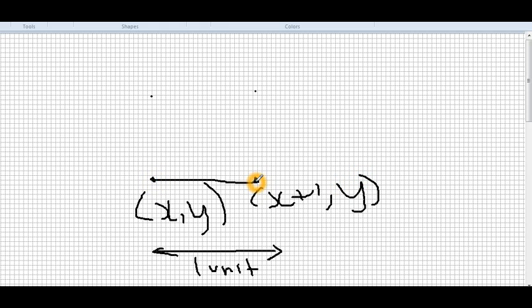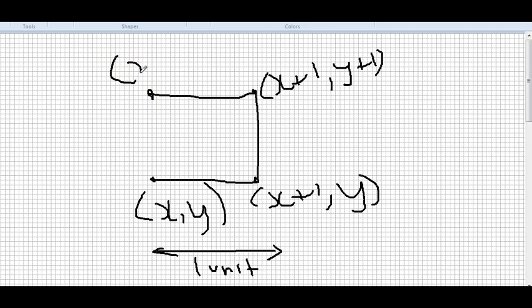and so we define these 2 points, and these will be joined because this is a loop of lines. And so the next point should be this, which will be x plus 1 comma y plus 1, because this distance is also 1 unit because this is a square. And the next point which should be joined is this, and so this will be joined when we supply a point which is x comma y plus 1, and these are the first and the last vertices.